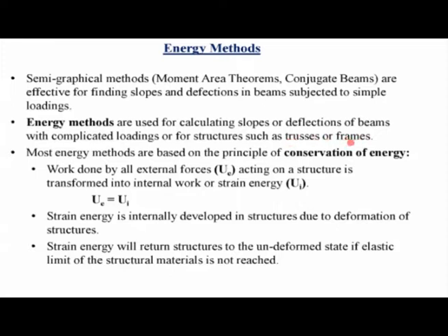It can take into account the deformation of frames, but you will see that the energy methods that we are going to learn today are more effective for calculating the deformations of frames because they take into account the bending deformations and in addition the axial load and shear deformations.